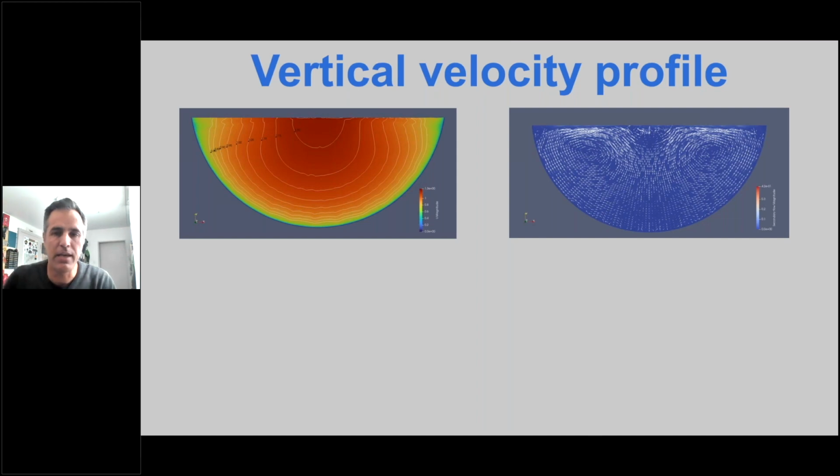urban environments and to the calculation of the depth average velocity, when we see that the ratio between the canal height and width changes, so when it's getting narrower, we can see that there are secondary currents of the flow, they produce sub-surface velocity maxima. So the maximum velocity is not at the top of the flow. So converting from surface velocity to depth average velocity is a bit more complicated.